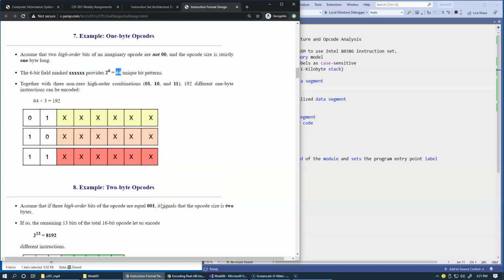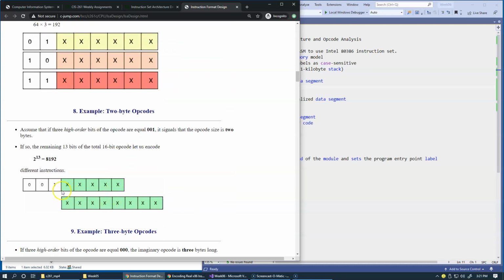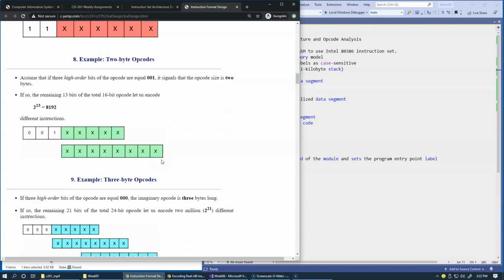And at the same time, if we have these 5 and 8 bits, which altogether is 13 bits in these 2 bytes, we can decode as many as 8,192 instructions. So this is an idea of instruction expansion, because when we design our instructions, we may not initially allocate all of these 8,000 instructions, but at some point we may start running out of opcodes that we want to be adding to our system.